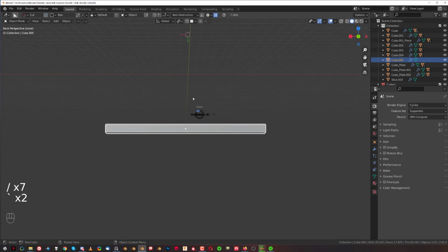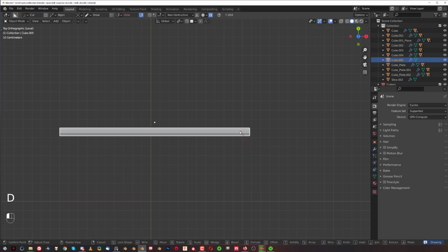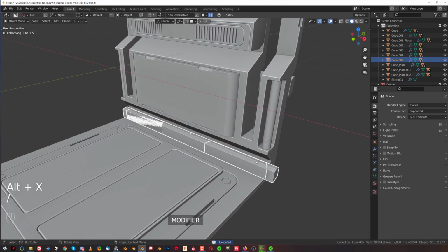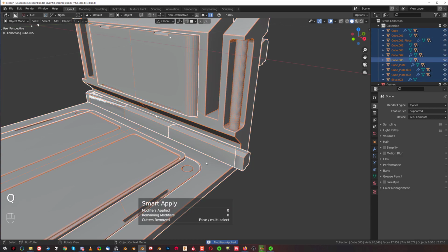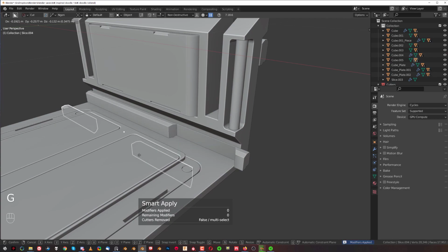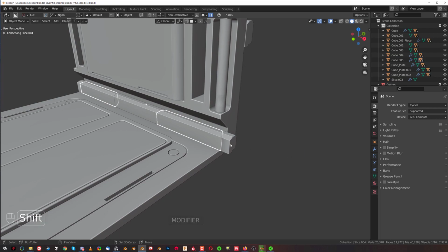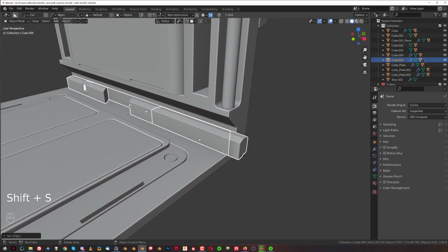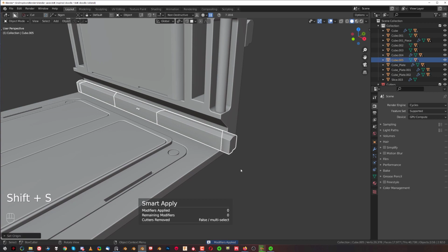We could panel this thing up, so go to the top view, orthographic D, and cut some stuff in it, like that, right, with X, boom, and copy to the other side, and select everything, and operations multiply. We have some double geometry on here. Probably this one is not mirrored, there we go, because it was sliced. And then select all of them, and Shift S to Geo. We need to apply everything again because of mirrors. Shift S to Geo, there we go.